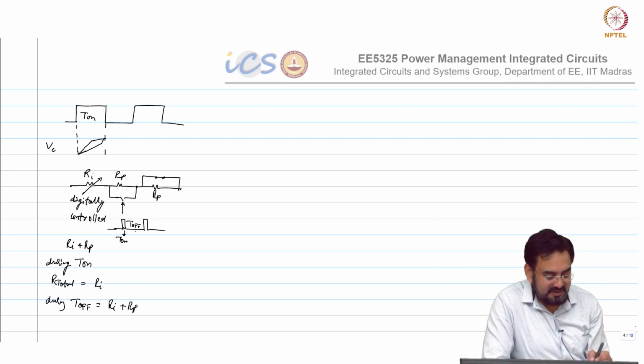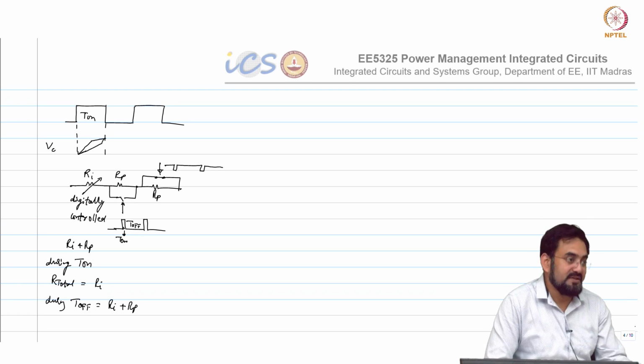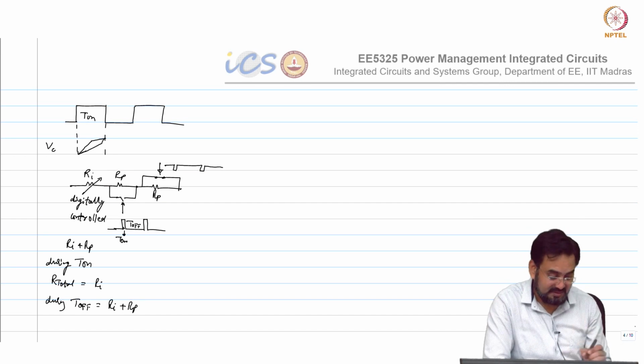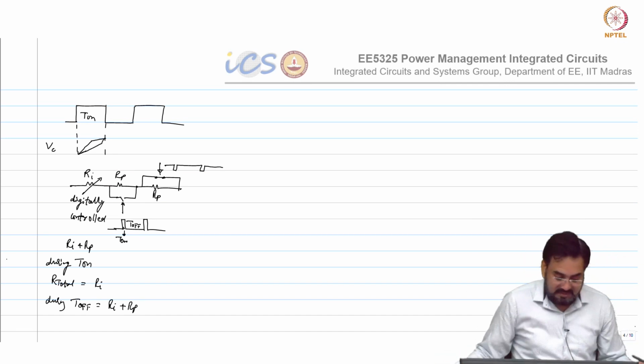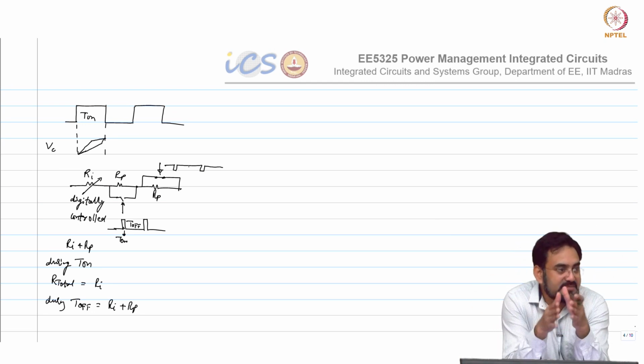correct. So during off time you will still get Ri plus Rp, but if I open this for a very short time like this, then during this it will open and add it up. So you will get Ri plus 2 Rp during that short period, and that is how you control the resistor. And once you lock in the frequency with some phase difference, this pulse width will remain constant. If there is a frequency difference, then every cycle this pulse width will keep changing.